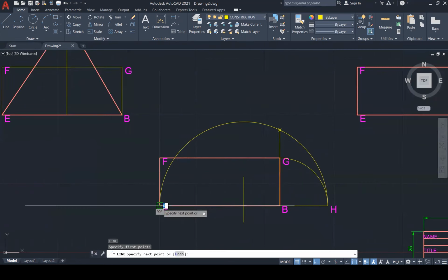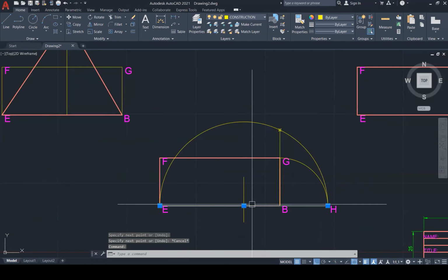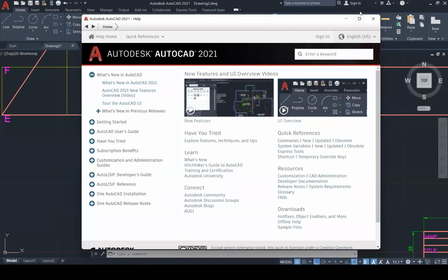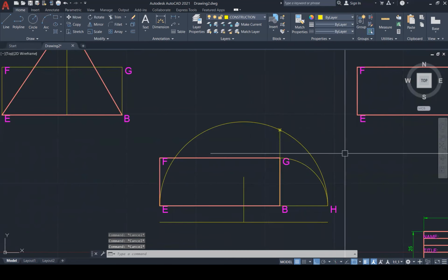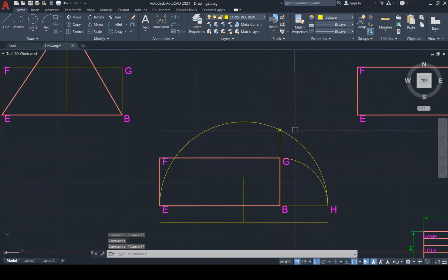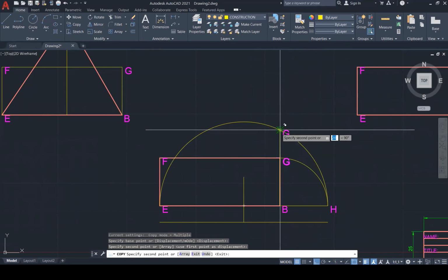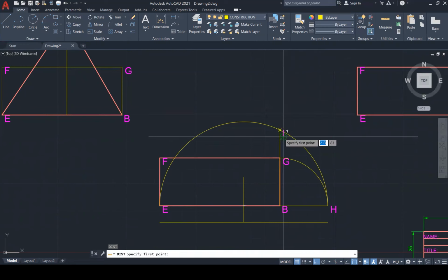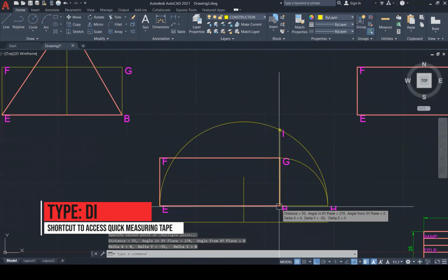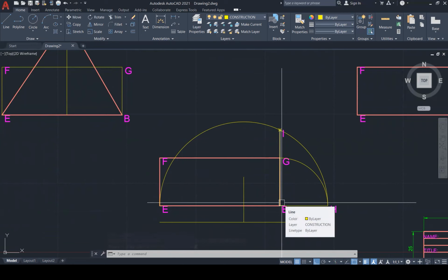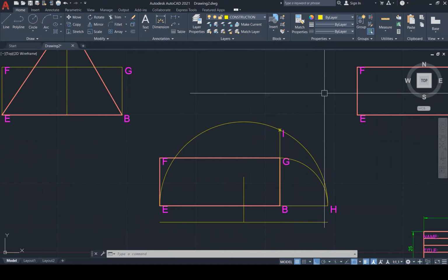And so that we know this is halfway, I'm going to draw a full line here. This line down. So that's how we know that's halfway. Okay. So the distance between B and this point up here, which is I, I'm going to copy that over. That will be point I, right? Distance between I and B is 55. So that means the side of our square is 55. So I just have to produce a square that is 55 millimeters.